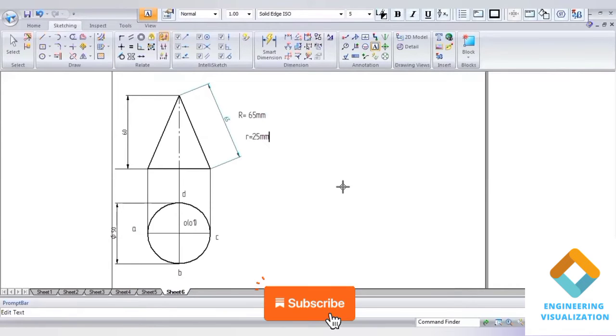To find out the development of this, we have the formula, that is small r by capital R into 360 degrees. That's how we can find out the development of the cone. Remember it: small r by capital R into 360 degrees. Using the calculator you can find out the angle. The angle we are getting is 138 degrees.